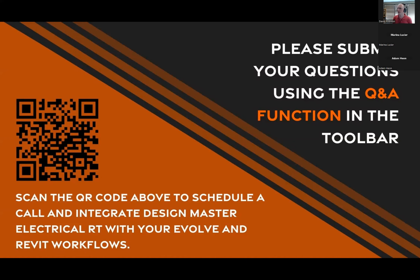Is the Design Master schedule bi-directional, so you can change data in the schedule and it will modify the parameters associated with the modeled element? That's a good question. All of our information is being exported as a shared parameter. So it shows up here as a shared parameter on the device. And then you can create all your schedules, the voltage drop schedule, the conduit schedule, fault schedule, based upon this. You don't make changes here though. So if you come in here and you type in a new wire size, that's not going to work.